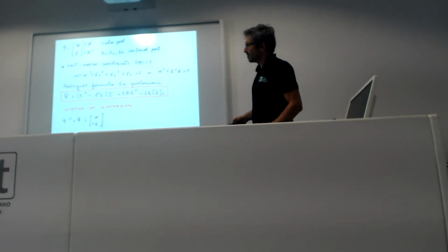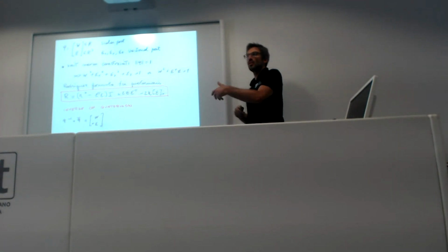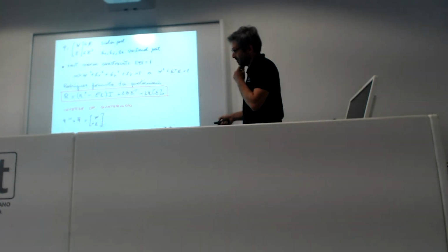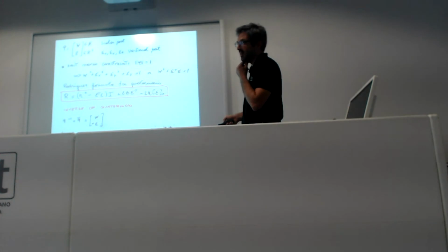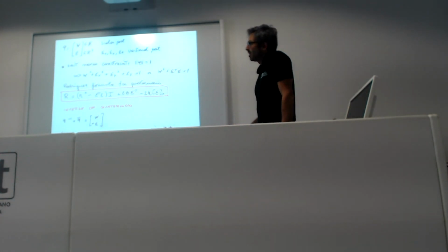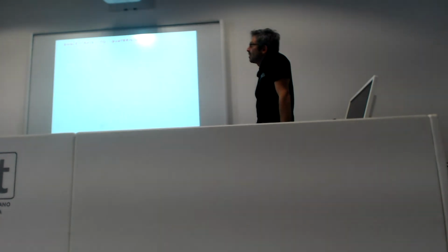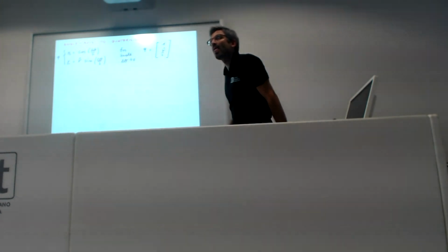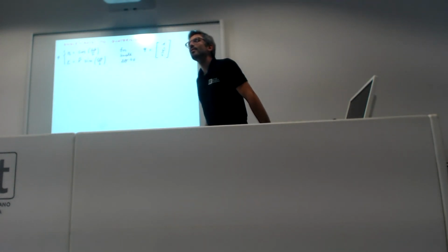The inverse of a quaternion just changes the sign of the vectorial part. So the inverse of a quaternion is the opposite rotation. You invert the vectorial part, and you can see that if you flip also the scalar part, you get the same orientation corresponding to the quaternion. You can also map the quaternion to the angle axis. For small rotation, you get this. Having 2 quaternions with the same orientation is going to be a problem.